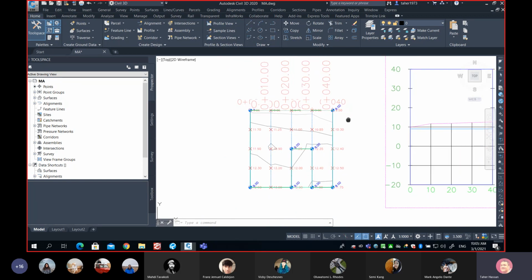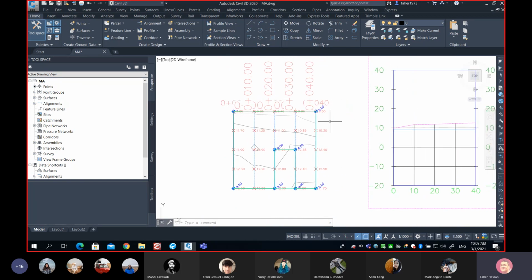If you remember, something I would like everybody to understand is that the location of the alignment, the orientation of the alignment, the direction of the alignment, all of those are your choice. In my demo here, I chose my alignment on the north side, going horizontal from the west to the east. Can you solve the same problem using a different alignment? Yes, you can. For example, you can choose your alignment at the center or at the south. You can even turn your alignment vertical. The thing is, once you make a choice, everything will depend on your choice.